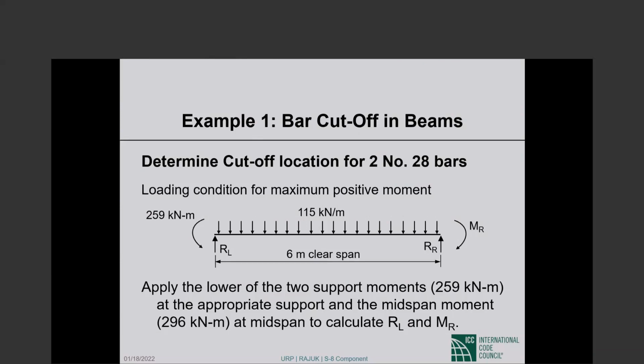Okay, this moment we did not take from page 1 because this moment and the two moments on page 1 are not simultaneous. Those are estimates of the largest moments that we should design for. They do not exist at the same time. So we have to calculate this from that. If the moment at the left support is that, what is the moment at the right support? That has to be calculated.